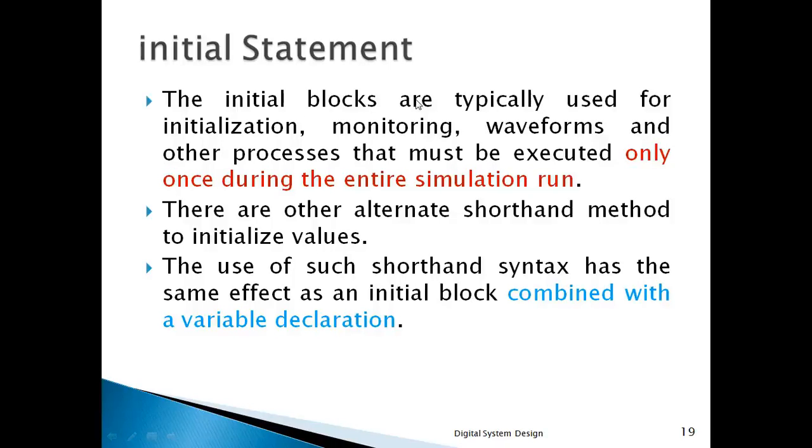Next, some further explanation is given. Initial blocks are used for initialization, monitoring, waveforms and other processes that must be executed only once during the entire simulation run. Other alternate shorthand methods to initialize values are also used. The use of such shorthand syntax has the same effect as an initial block combined with a variable declaration.